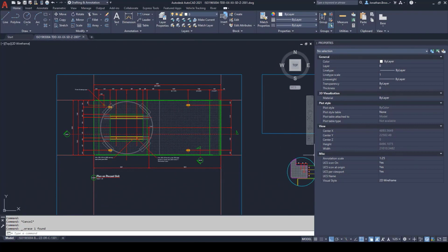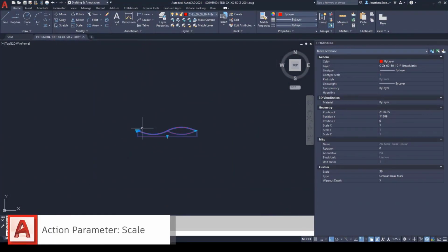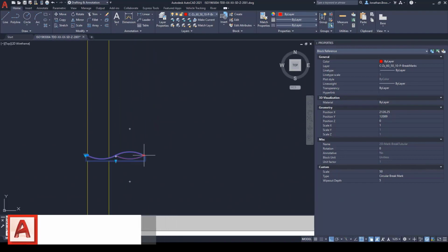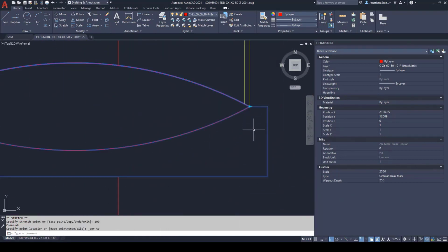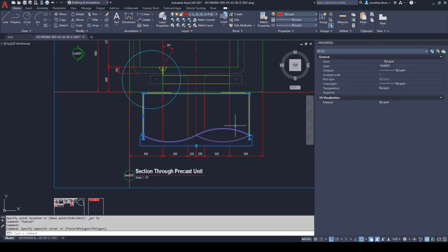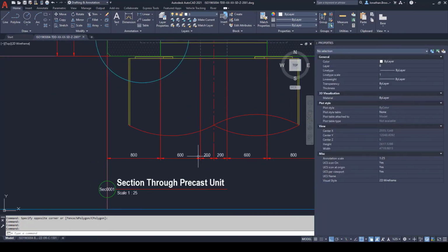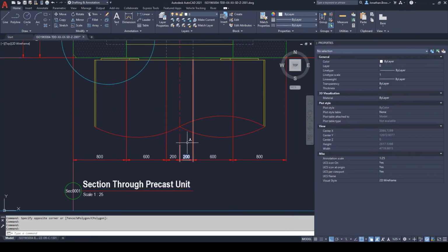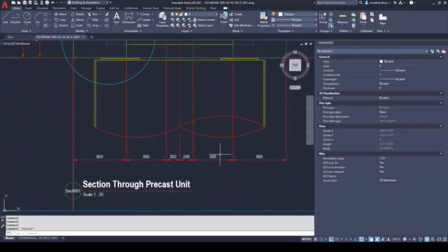structural projects and beyond. By using the Scale Action parameter, users can easily scale objects and symbols using a reference node inside of the block. This workflow enables users to efficiently and accurately scale objects between 2 points or scale the object by a numerical value. Its application in regards to civil and structural engineering could be for blocks containing symbols representing items that change in size, such as brake line indicators and doors or windows.